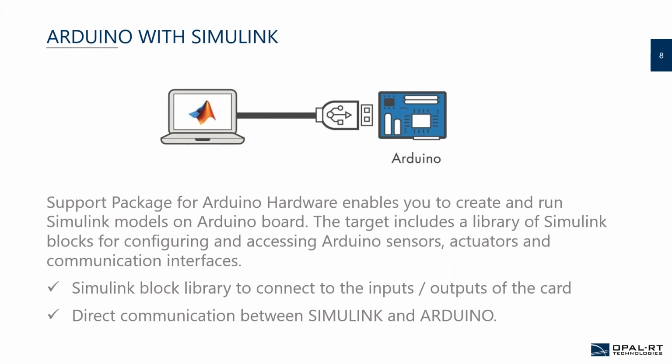MATLAB Simulink. MathWorks thinks about programming the Arduino card just by using your normal MATLAB Simulink model, and then you can directly upload it to the Arduino card. There is a support package for Arduino hardware. It enables you to create and run Simulink models on Arduino boards. The target includes a library of Simulink blocks for configuring and accessing Arduino sensors, actuators, and communication interfaces.